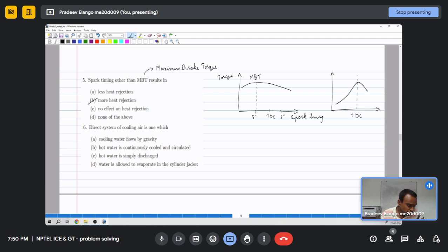So this is a motoring curve. Okay, and this is crank angle and this is pressure. And if you want to draw it in pressure-volume, it will be something going down, and while expanding, the pressure would have dropped because of the losses.